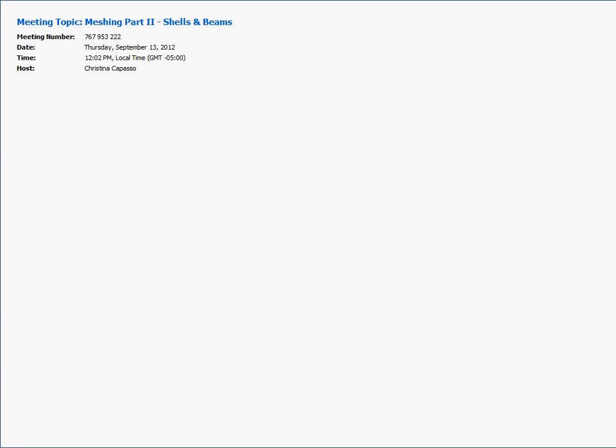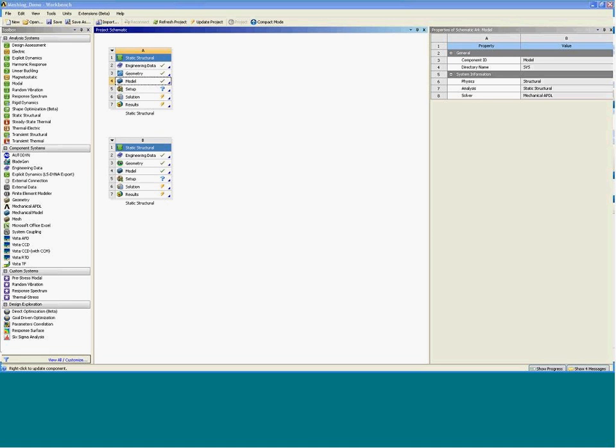All right, so this one looks like the majority is using the CAD system. That's definitely available to you. There's a mid-surfacing operation there, built into the CAD to bring over that geometry, as well as Design Modeler. Actually, none have used SpaceClaim, which is what I showed. Again, I only like to use that because the beam action utility makes it so easy to set that stuff up. But any will certainly work. So great. Let's go back to Mechanical now.